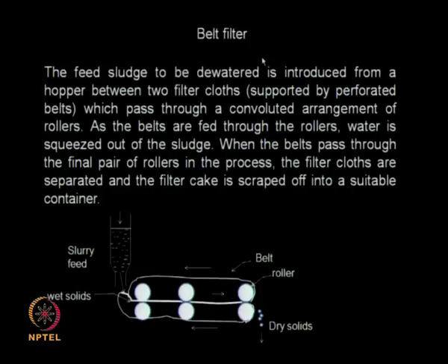So this is the advantage of it, and it is useful for dewatering of wet paste, soft paste and compressible paste. Here we can either have a scraping unit, or if the solids are not getting compressed, they can fall out on this side. So the belt filter is used as a continuous process, because here slurry can be fed in continuously, and then you continuously get the dry solids, which can be fed into a continuous oven or a hot air dryer and dried still further.